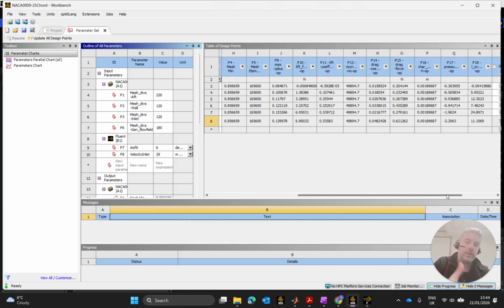We could see the 4 equation model is probably the best method to use there, because we clearly have turbulence occurring at these higher angles of attack anyway, and the transition equations are appropriate. As well as that, with a 2D well-defined structured mesh, there's very little else we could do with the spatial discretization or the pressure-velocity coupling.